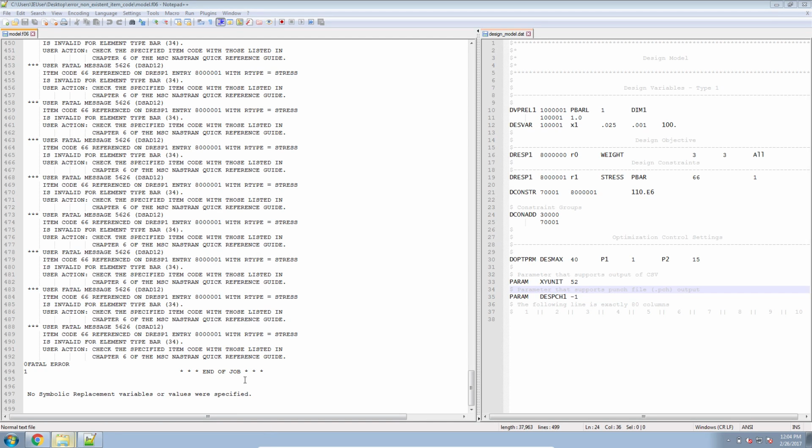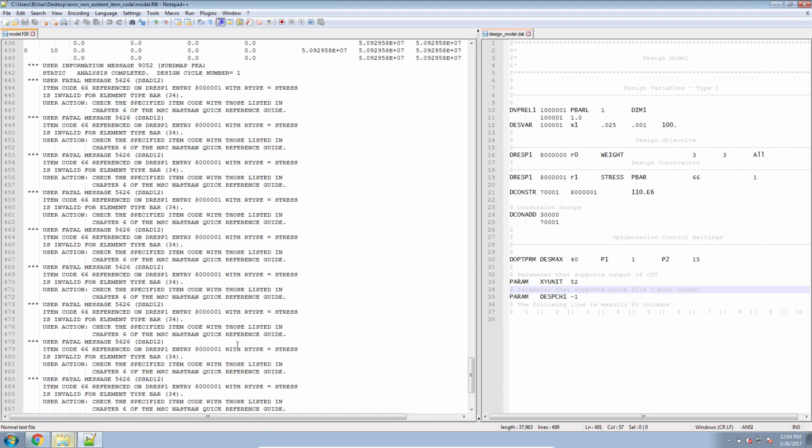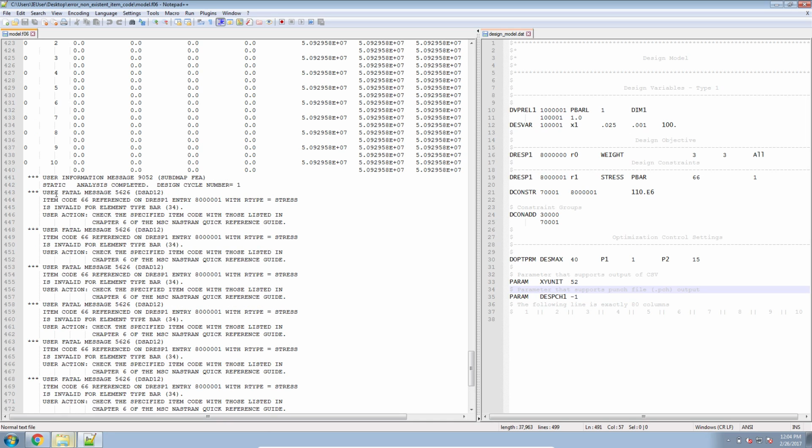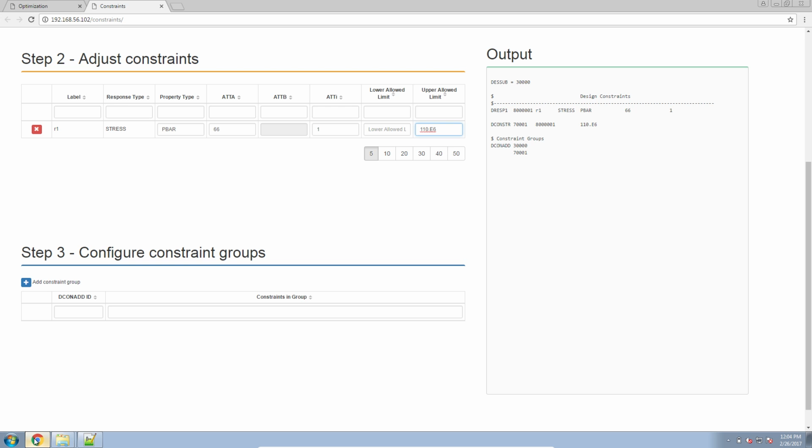In this video, we are going to work on resolving a new issue called user fatal message 5626, item code 66, reference on DRS1 entry with stress type is invalid for element type. So here, this message is saying that there is an issue with the item code I'm using. Let's go ahead and look at my web app.